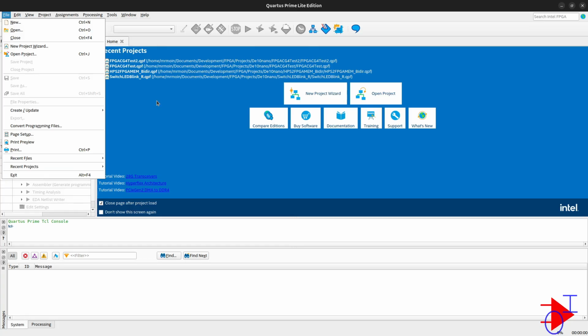For this SD card image, there is a separate FAT partition created that the HPS reads at its initialization, and it then picks up this RBF file and programs the FPGA. It's much cleaner. We don't have to worry about flashing our EPCS every time there's a new program. We just change that file, and the HPS takes care of the programming side.